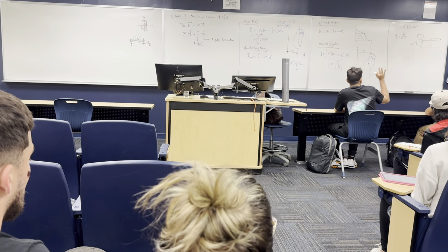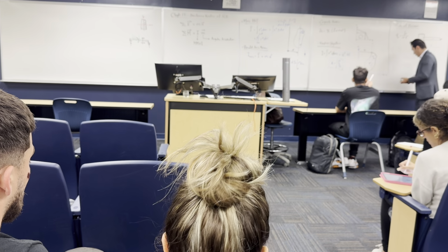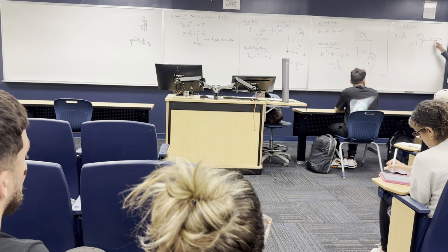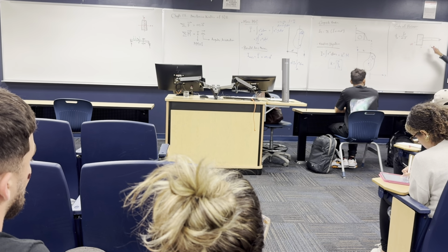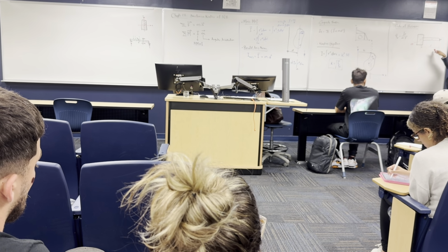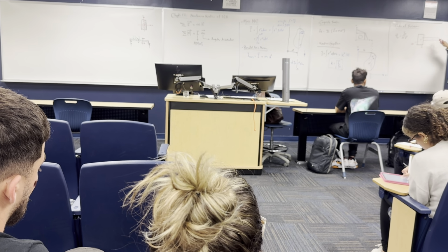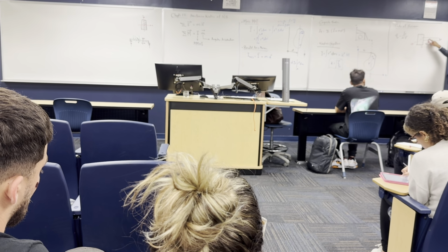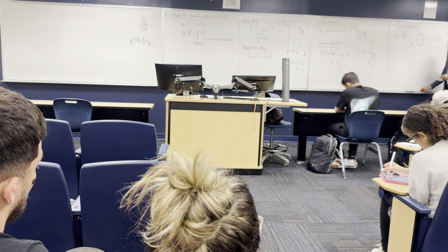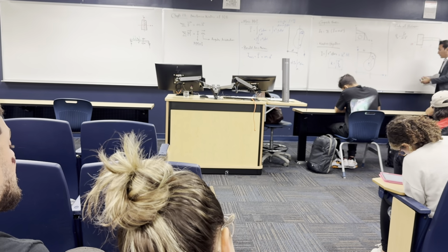We are going to have an example that clarifies how we can calculate. The inertia is with respect to point O, right? Yeah. So you have to do the parallel axis theorem. You can pick this point, you can pick this point, whatever point, but all of them have to be consistent. Y bar is measured from the point that you are taking the mass moment of inertia at, and this is going to be measured from the same point. You can take a point here or a point here, whatever point you would like to pick. Okay, so let's solve an example and see how the reality looks.